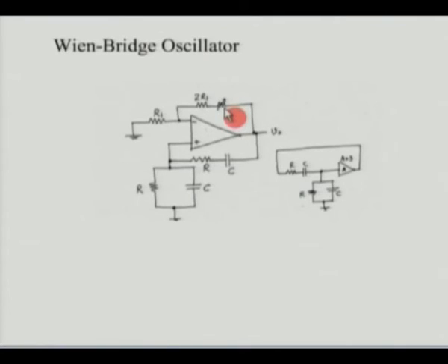If you just leave it there, you would see a sine wave just dancing. It might collapse, it might continue, and if you increase it further, you would see at some stage it is stabilizing. If you go further, it will get distorted. So this particular circuit is an extremely useful circuit. At the same time, it teaches you something very important, that this circuit cannot be used as a practical circuit, because you need to satisfy that condition exactly, which you can never do. We can't do it manually.